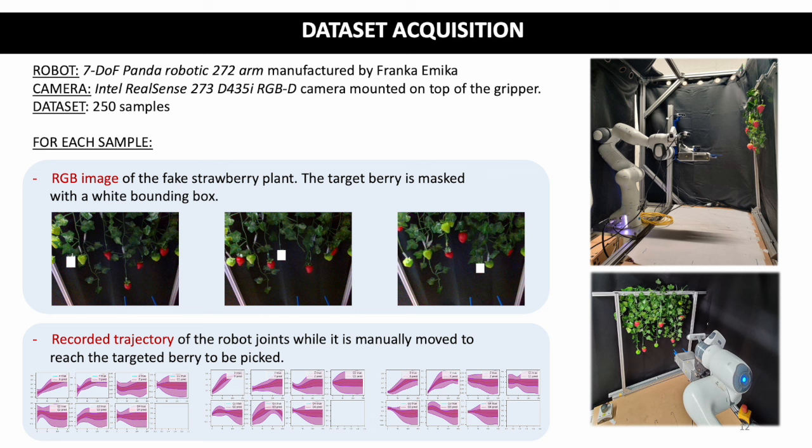We had a strawberry picking robot that we tested in a commercial field, and we had the problem of generating trajectories for each strawberry, but from different orientations, so that we can deal with occlusion. If a strawberry is behind a leaf, we want to reach the strawberry to pick it not with a straight line, but going around that leaf. That means we need to have a distribution of trajectories based on the visual information that we can sample and select the trajectories that go around the leaf.